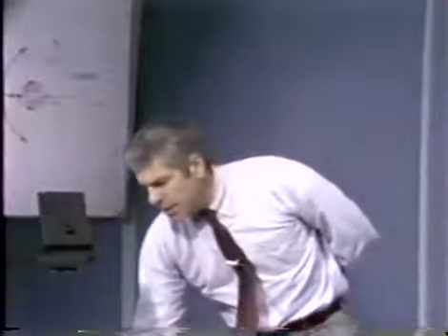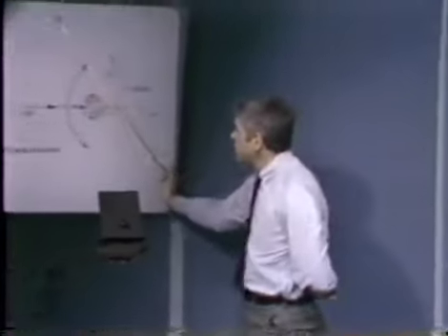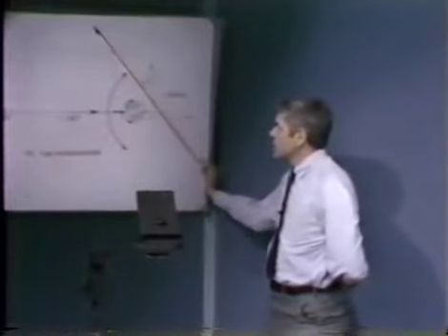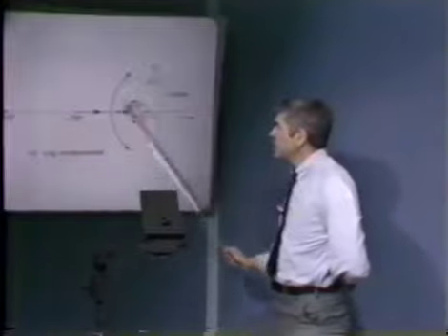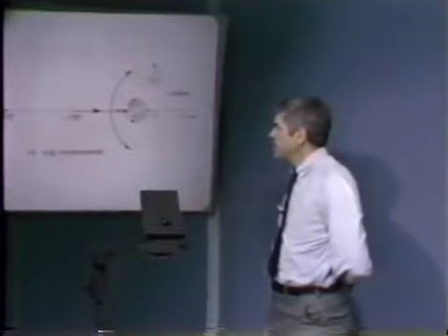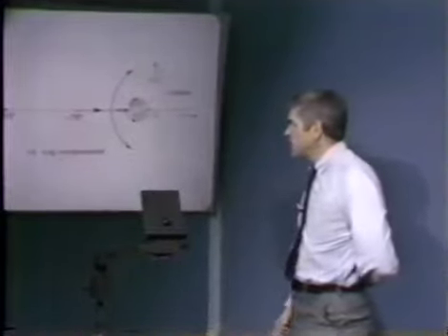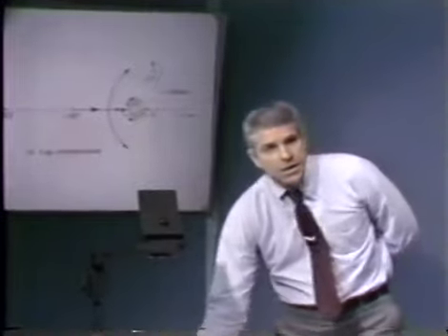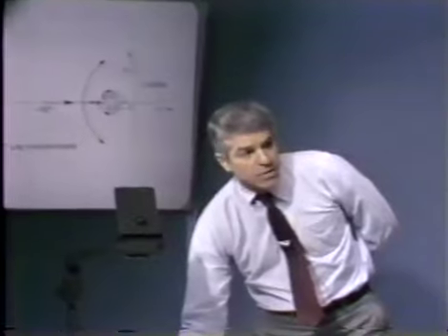However, if we kept track of A0 F0 necessary to get out to a given damping ratio, we'd find that we could tolerate considerably more A0 F0 in the lag compensated case than in the uncompensated case. In fact, about a factor of 6.2 greater A0 F0, equal to the alpha of the network that we use.